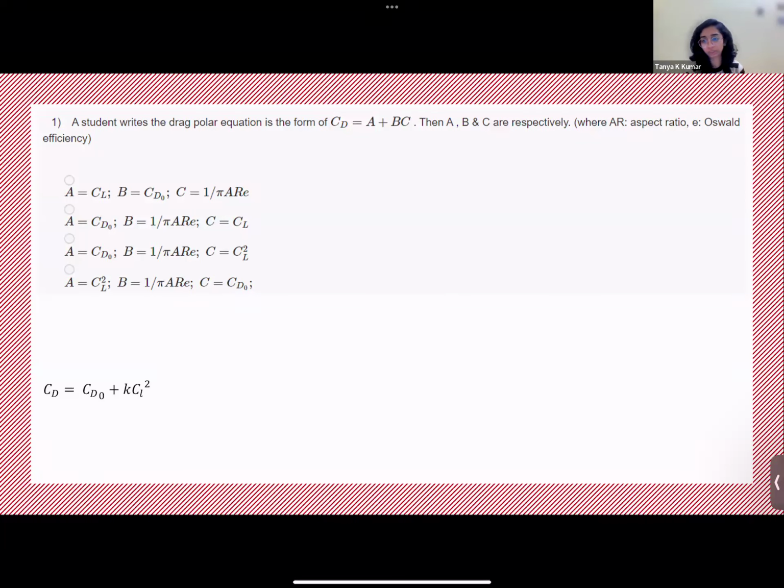Due to wingtip vortices. Yes, there are wingtip vortices. It occurs because the flow above and below the wing meet at the wingtip, and then it becomes an unsteady flow, and then you have vortices generated which travel backwards, and the downwash also creates a problem. So that's why there is a drag due to the lift generated, because of the uneven nature of the forces above and below the wing that meet at the tip. Okay.